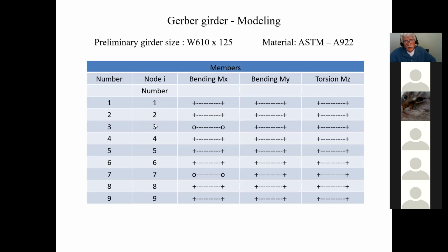Now the suspended one, what I'm going to do is make it pinned on both ends. I don't have to pin it there and pin it there. I only have to pin it on one member. I know that whoever takes this with the other teacher, I always see the students pin there and pin there. Don't do that. That's redundant, okay? As a matter of fact, some structural analysis programs cannot get rid of that redundancy, and if you do that, the program is going to crash on you. This program is sophisticated, and therefore it can overcome that redundancy. So when you want to pin something, I either pin it on this member or I pin it on that member, but I do not pin it on both members, guys, okay? I'll tell you that right now.